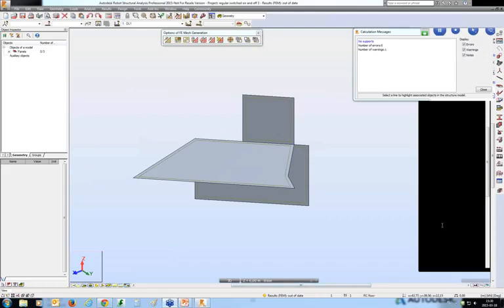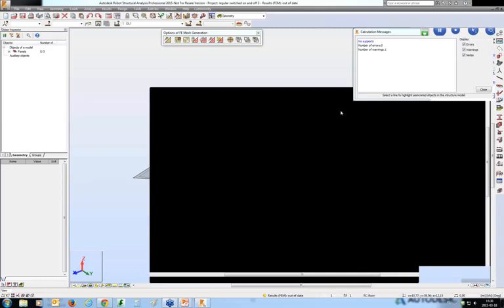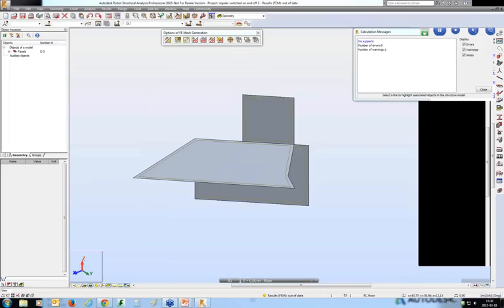The next one. Do you have some recommendations for analytical models in Revit? A lot of problems you showed are caused by analytical model issues. Yeah, I think the first option that I covered, the adjustment to structural axis, is the one to start with. My assumption is that you have an incorrect analytical model in Revit, which causes issues with meshes in Robot.